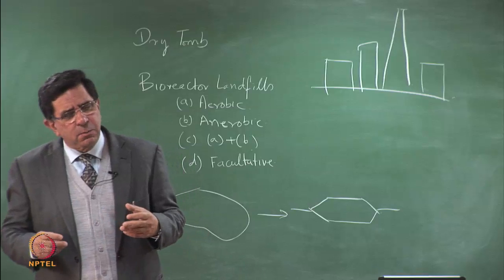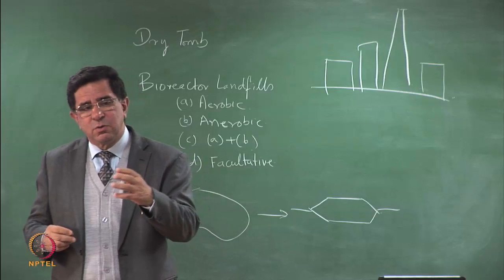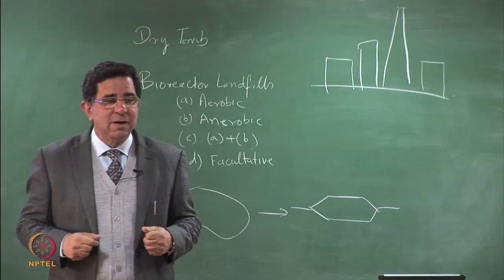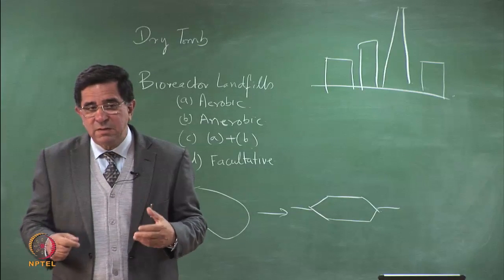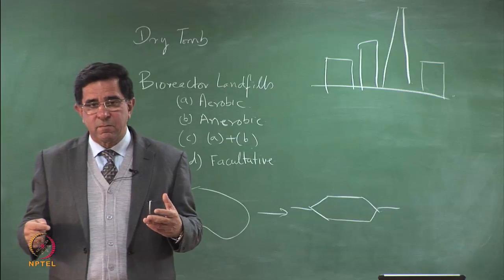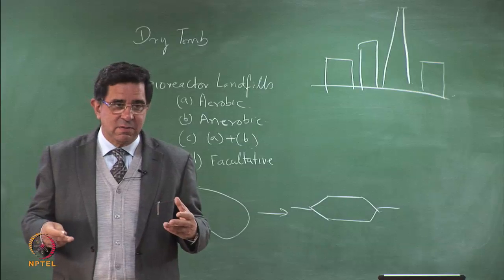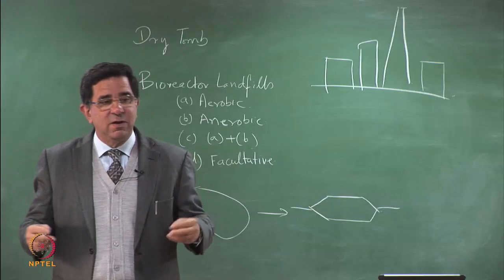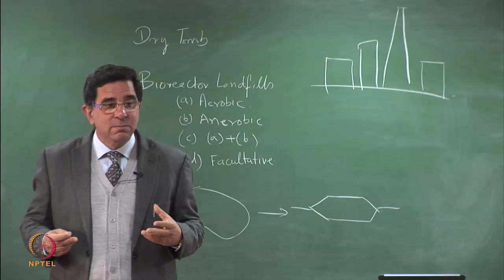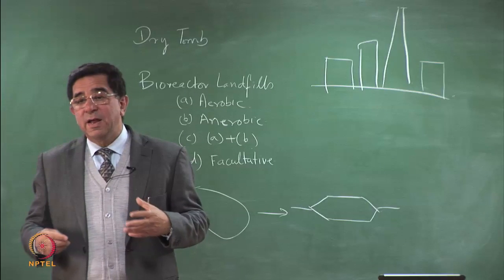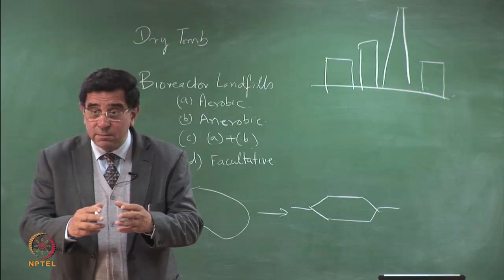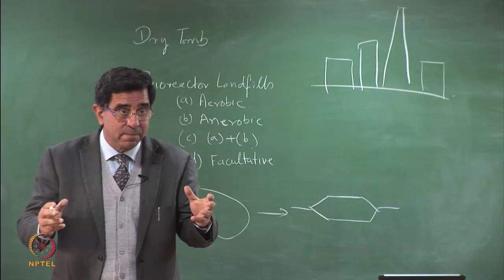How much time does it, suppose some biodegradable waste comes into a conventional dry tomb landfill. How much time do you think it stabilizes in? Weeks, months, years, tens of years? Well, tens of years. I can assure you that in a dry tomb landfill in which water is not coming in, you don't have enough moisture to degrade. So we have in dry tomb landfill, the waste stabilizes in tens of years. Therefore, biodegradables should not come in.